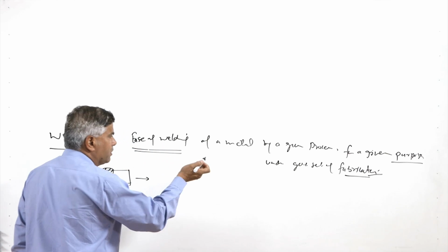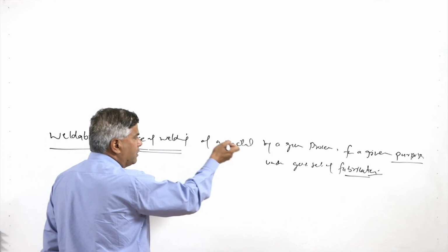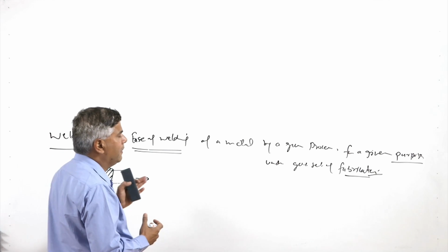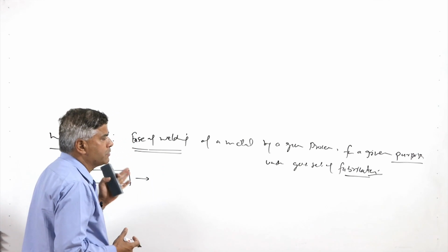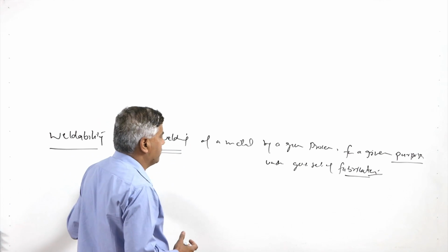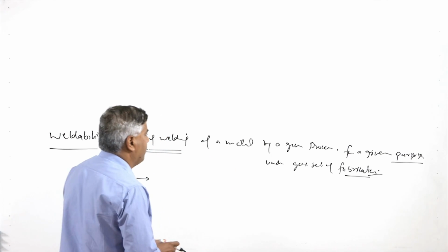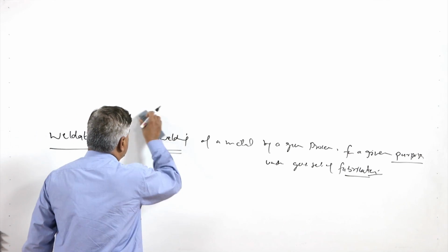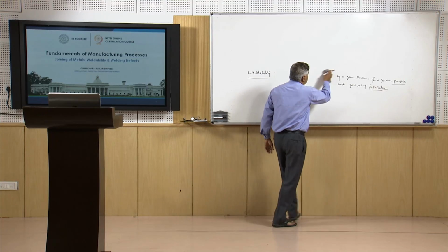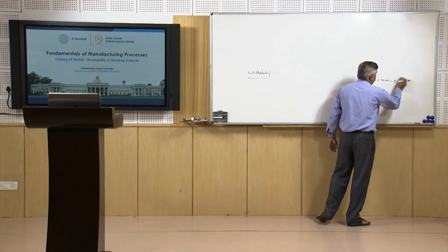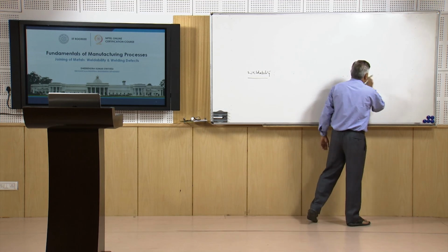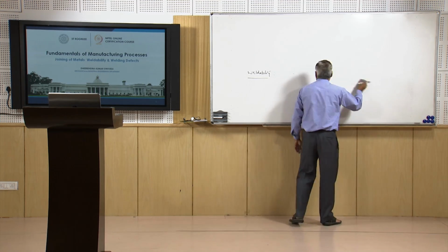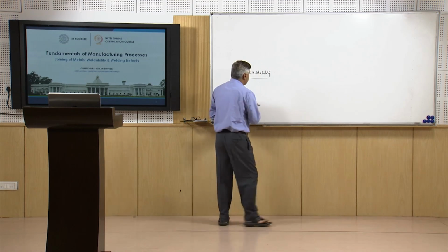So, with the change of purpose weldability changes; with the change of welding process being used for joining a metal, by fusion welding or by any other process, it also affects the weldability. Similarly, the fabrication conditions affect the weldability. To a great extent the ease of welding is influenced by the properties of the metal which is being welded, and apart from that it is also assessed in three ways.